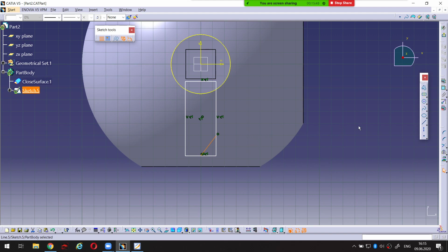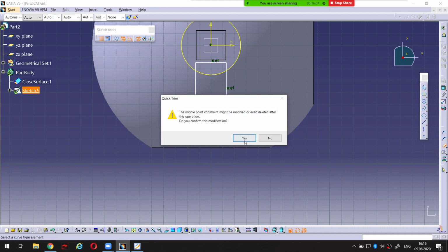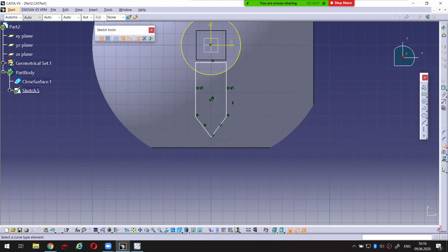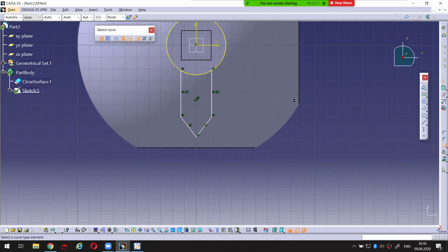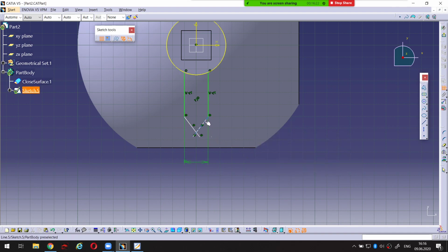I create my sketch using approximate dimensions, I guess. It should be something like this. So like this. I don't need these parts. This one, this one, this one, and also this one, and probably even this. So, what about dimensions? I think that the thickness or the width of this sketch should be 20 millimeters. Okay, and the angle between these two should be 90 degrees.